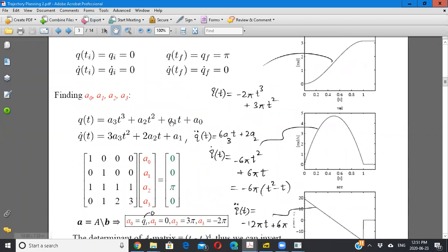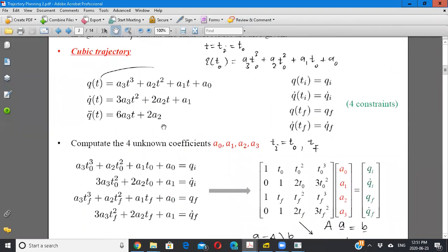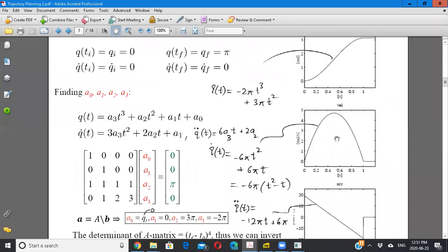So this is called trajectory planning, or trajectory generation. And the trajectory that we have generated is called a cubic trajectory. Can anyone tell me what the maximum velocity is? What is the value of this maximum velocity? I can see here from the plot that it's 4.6 something, but how do you find it mathematically? Hello? Can anyone find the maximum of an arc?